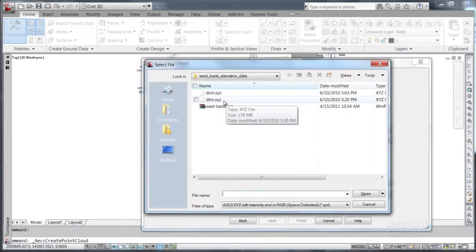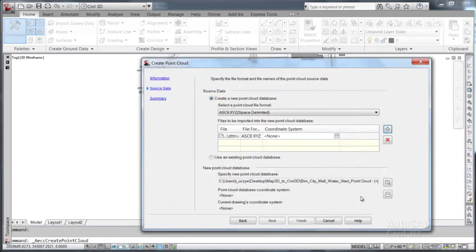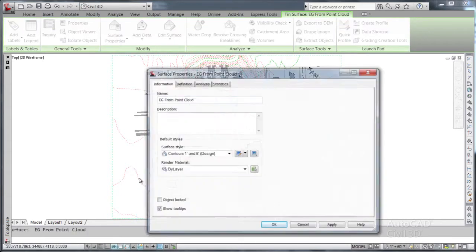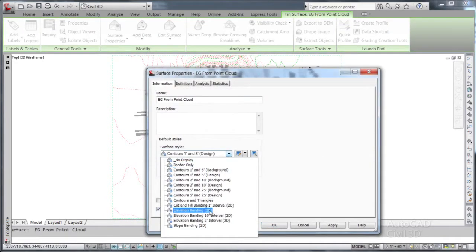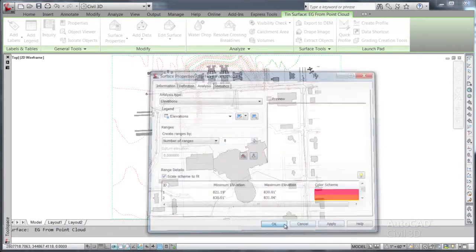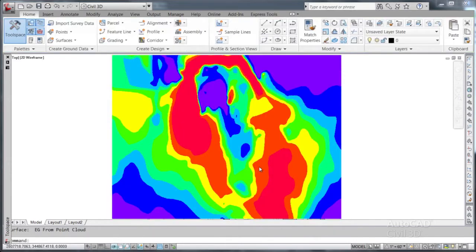Using surface data captured in the planning phase in the form of point clouds, you can build the existing ground surface, then style the surface by elevation to show low-lying areas. Then, analyze the natural surface water flow of the existing ground using the water drop tool and labeling spot elevations of the existing ground surface.